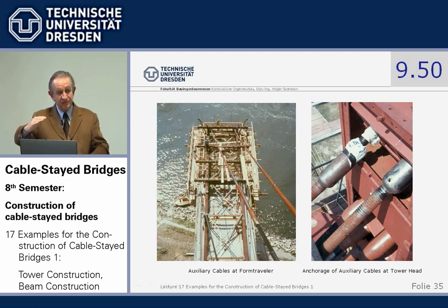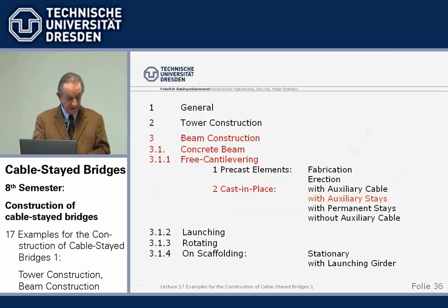So even for the very first element where we have steep cables and the force is low, we have to use cables so big that they can take up the 3 times bigger forces in the final stage. So it's time consuming and costly. And the idea of reusing auxiliary cables normally doesn't work. This was the first step with auxiliary cables.